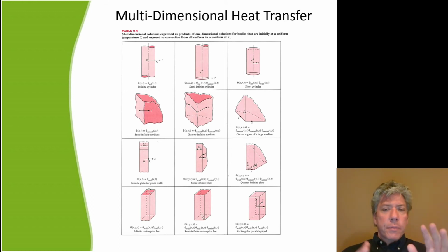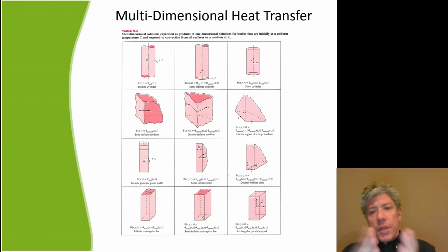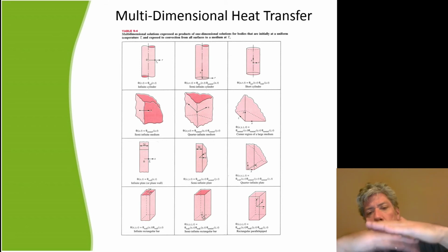Okay, so the way you can come up with it is pretty simply. Start with the first model, the one that you know. The infinite cylinder only has heat transfer in the radial direction. So you know that the other two cylinders are going to certainly have radial heat transfer. But then look and see what the next body is, the semi-infinite body. See how it's oriented relative to what we've already got. And the semi-infinite is oriented this way because there's the plane face.